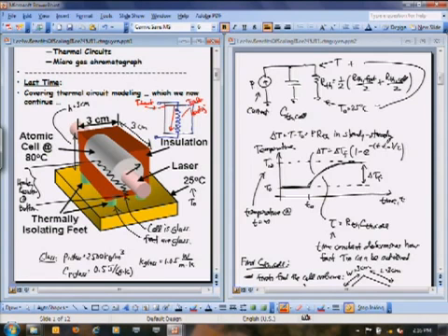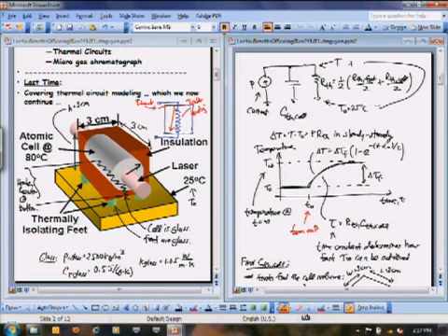This is something everyone should have learned in their first circuits class. If I gave the input power a step response where I turn on the power right there at T0, then this thing is going to rise in temperature, just like this RC circuit, with a rise time dictated by the time constant of the RC circuit. And a temperature that's sort of predicted by how much power you're putting into this thermal resistance.